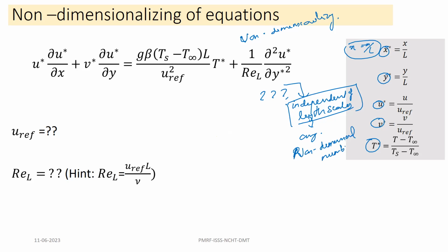So if two systems, system A and system B, have similar non-dimensional numbers characterizing them, say the non-dimensional number is called D here, and here also it is characterized by the non-dimensional number D, then they will exhibit a similar kind of behavior in natural convection or in any system. So it is irrespective of the size or the dimensions. So it's a scaling analysis.